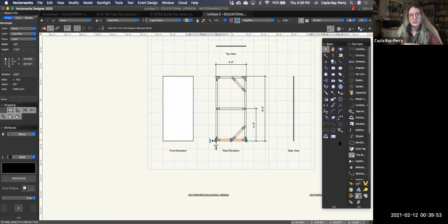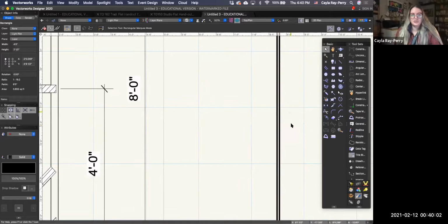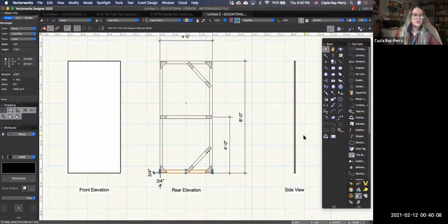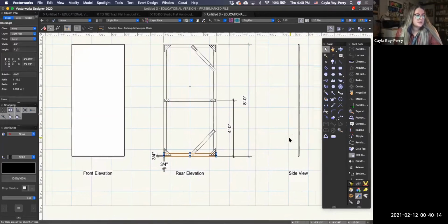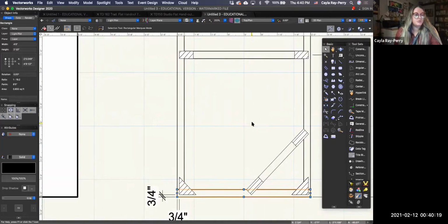For you to choose to not do that in order to make it so that it makes more sense to the viewer. Drafting convention says that this should be a thick line, but if we can't see it, then it doesn't need to be a thick line. If that's going to render this incomprehensible, then that defeats the purpose, right? So it's always important to consider your viewer when you're going to be drafting something.